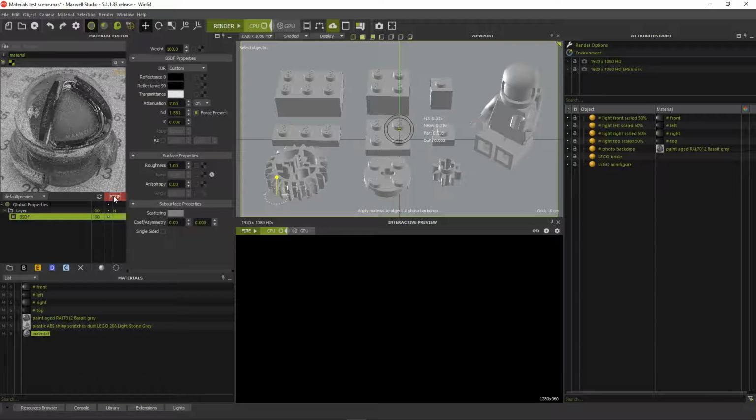If you want to save a material for future use, you want an accurate preview icon, so you or your colleagues know exactly what the material looks like. Because of the size of the symbol and its baked-in UV coordinates, and your objects having different dimensions and wall thicknesses, it is best to use the relative texture mapping method and keep repeat and bump strength as shown, not for the render, but only the preview icon.